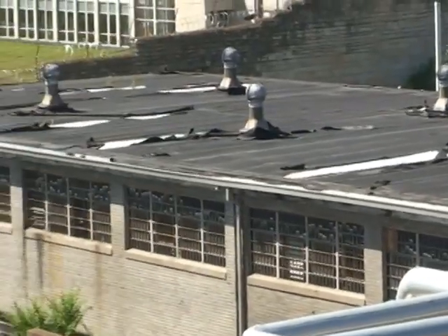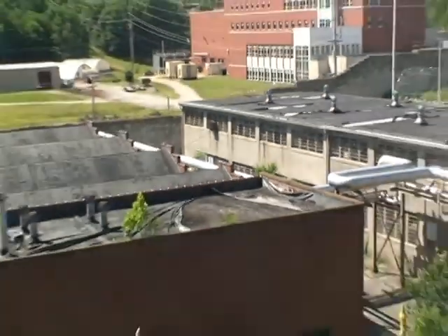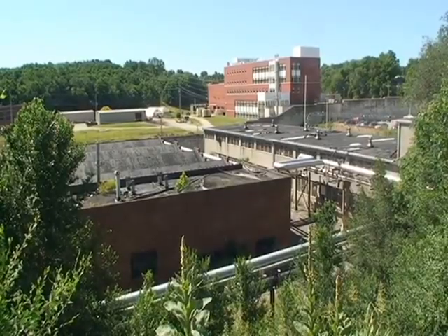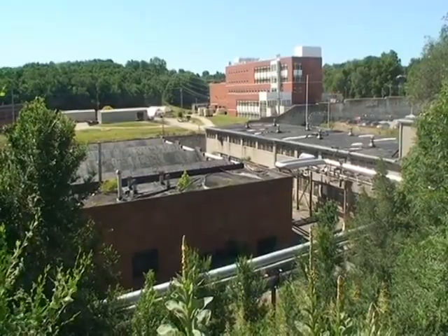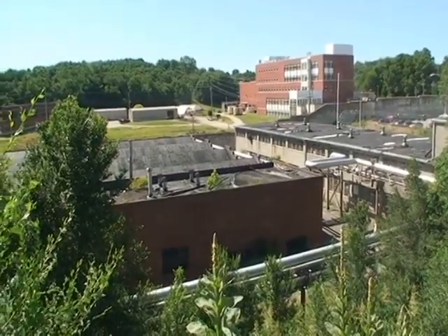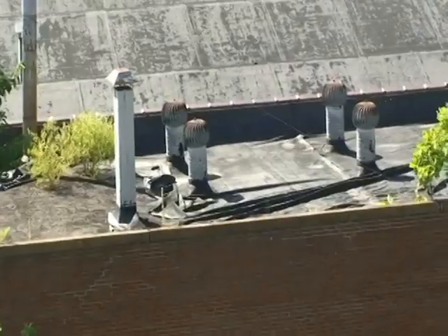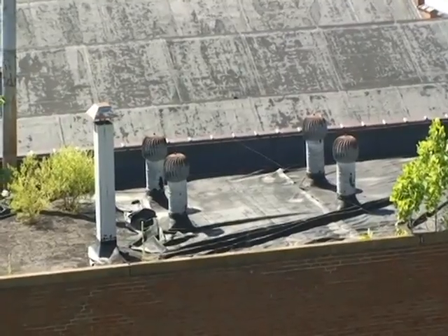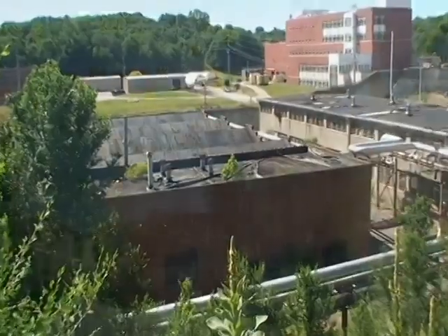For roofing materials, if it's in good condition and it's going to be removed using either a roof plow or else manual methods, it's considered unregulated. If you ever use any kind of a saw or a roof saw on that, you've got a different threshold to consider. Rather than 160 square feet, which you normally look at for NESHAP purposes, it's 5,580 square feet specific to roofing. So if you're going to saw a roof and it's got asbestos in it and it's more than 5,580 square feet, you're going to have to use a registered contractor.